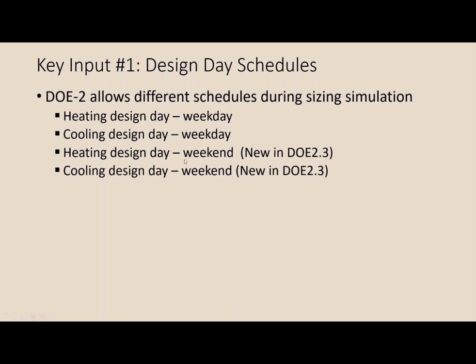Whereas in DOE 2.3, there's this added feature of having different design day schedules for the weekend so that you can simulate the Monday morning startup after things are set back over an extended weekend period. So that enables you to capture this kind of higher peak loads that happen on Monday morning startup.